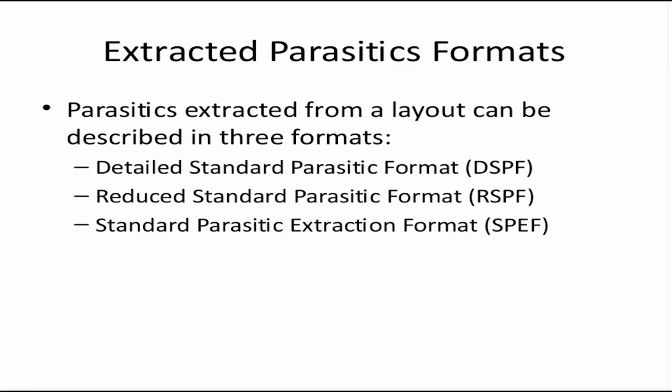Now these parasitic files can be in one of three formats. Either they could be in the format DSPF, detailed standard parasitic format, or RSPF, reduced standard parasitic format, or SPEF, which is standard parasitic exchange format. The tool will extract the data and put it into a file which will conform to one of these three formats.